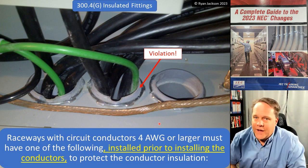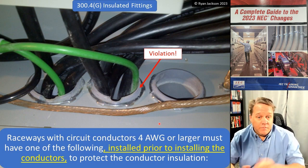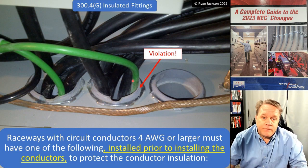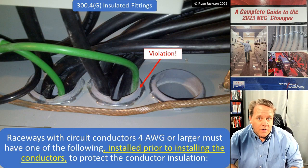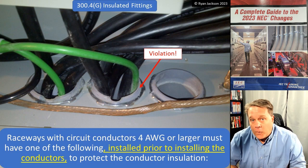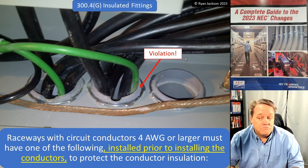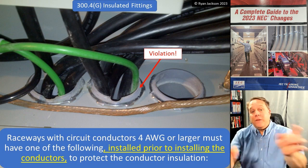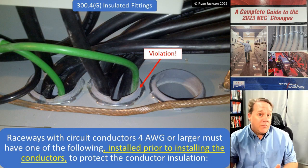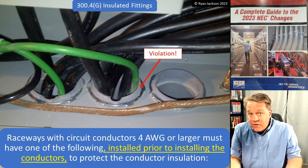Now here's the problem I have. Put on your inspector hat for a minute. You walk up to the job and you see this installation right here. And you write them up and you say, hey, you got to have a plastic bushing. And you have to install it before you pull the wires. And the guy says, well, the wires are already here. Okay, well, what's the next part of that conversation? You going to make them rip the wires out, then put the plastic bushing on and then re-pull the same wires? So subject them to the potential of damage twice instead of once?